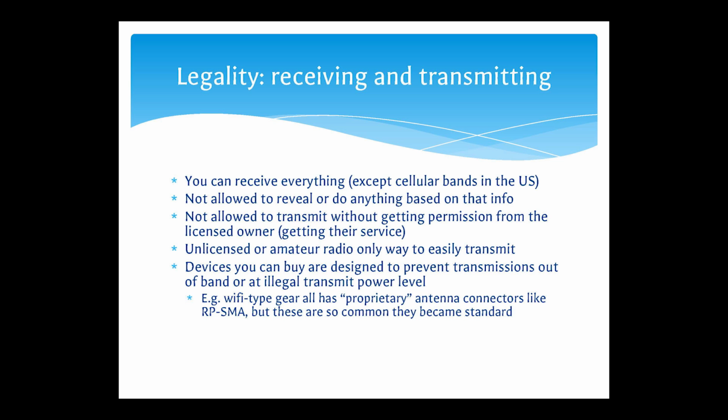For example, one of the requirements for FCC certification for Wi-Fi gear was that they couldn't use common antenna connectors, such as the N connector. So a large amount of Wi-Fi gear started being sold with RP-SMA connectors, which the manufacturers called non-standard, so that people couldn't plug external higher gain antennas into the Wi-Fi products. And then everyone had RP-SMA connectors, and now that is a standard.